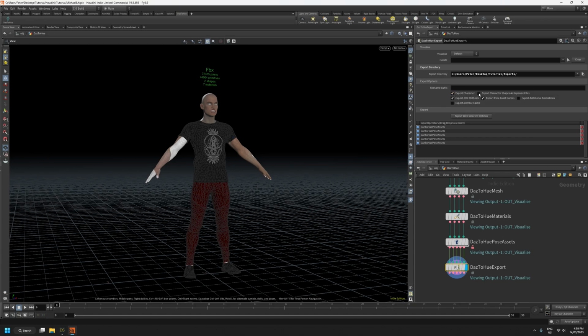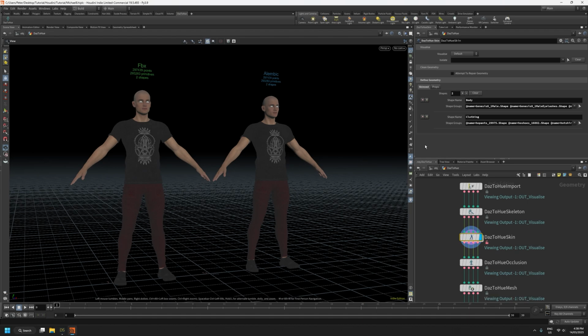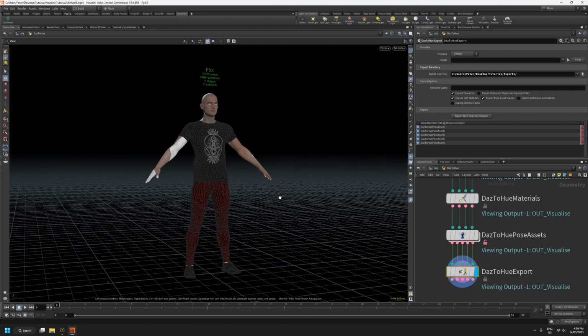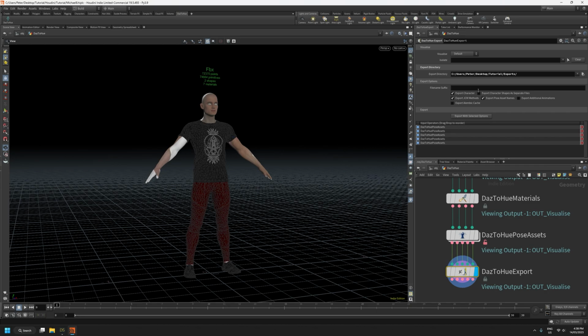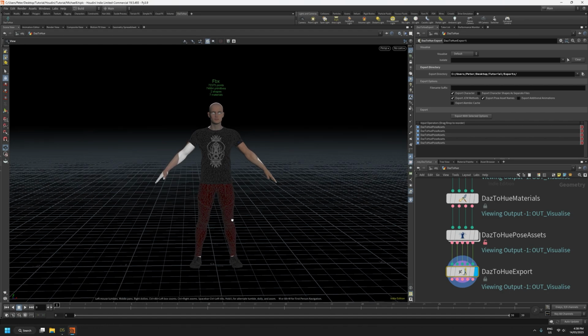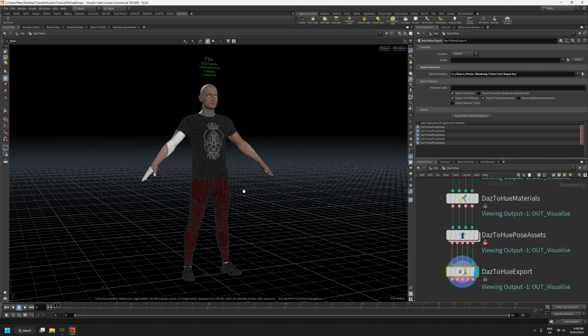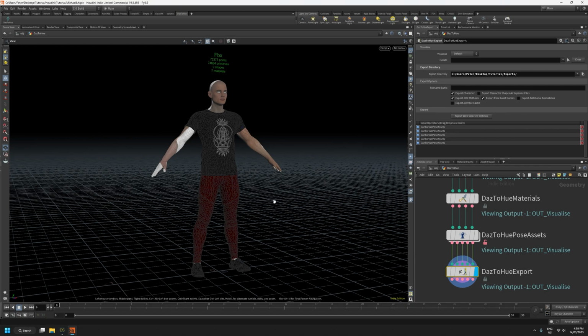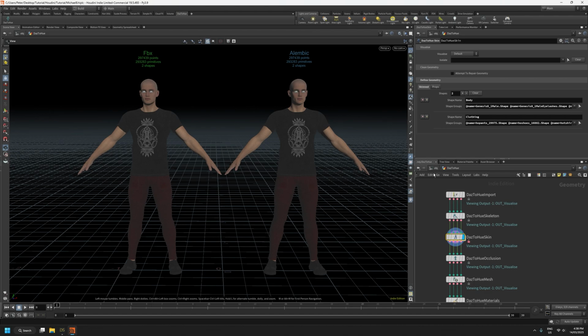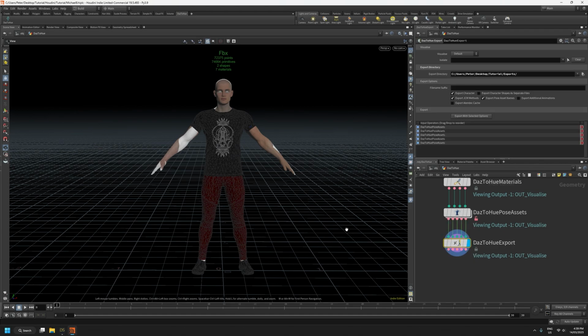If you are exporting the character, you also have the option to export the character's shapes as separate files. So if you'll recall back when I was talking about the skin node, we defined two skin geometry shapes called body and clothing. If we selected this option, then it would export two FBX files in this case, one called body, one called clothing. Both of those would have the morph channels embedded as well as the range of motion animation. And as I said at the time, that's a good option if you're wanting to go down the modular clothing path in particular. Obviously back on that skin node, we could have broken the clothing down into shirt, pants and shoes as separate shapes, and then it would export all of those as separate files. For now, we're just going to leave it with the two shapes.